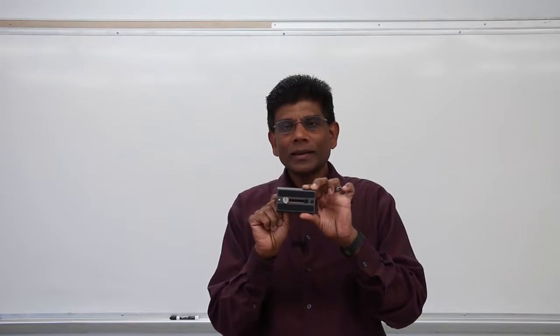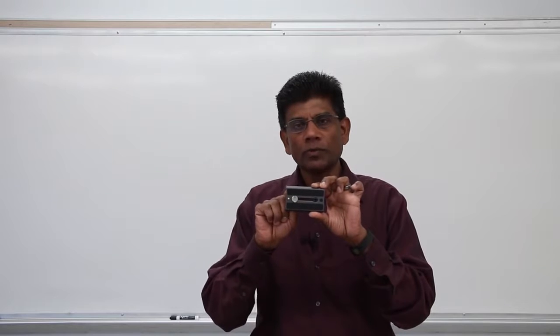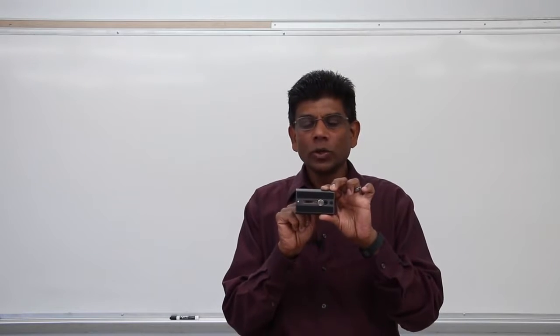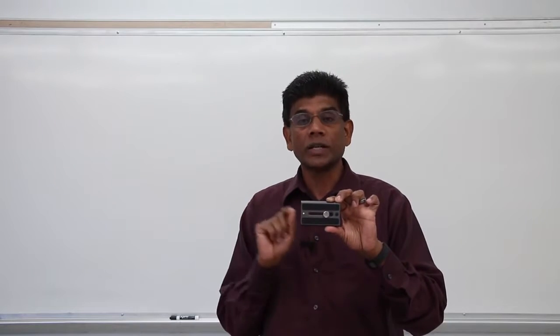So it's like a pin support, but in addition to allowing rotation, the slot allows this body to move along that, which means this is not just a pin support. I call it a roller support, which allows a rotation as well as a movement along this. It doesn't allow you to move in the vertical direction. So this roller support will actually create one reaction. Again, we are going to take a closer look at that in a minute.